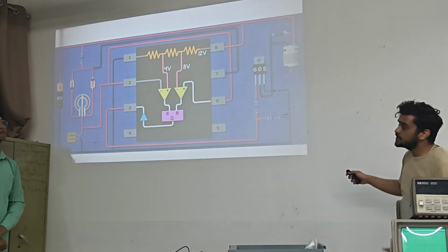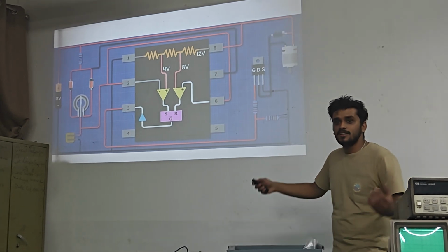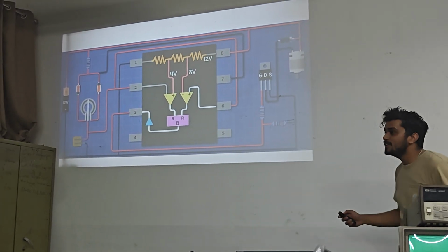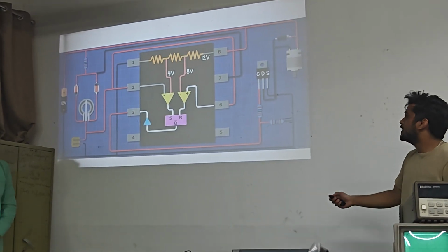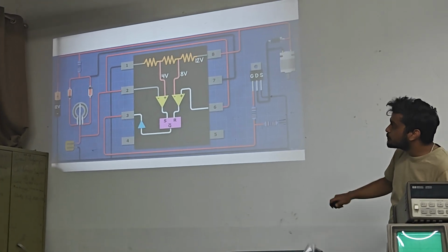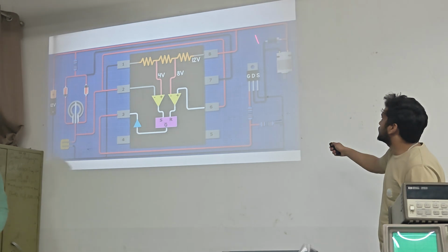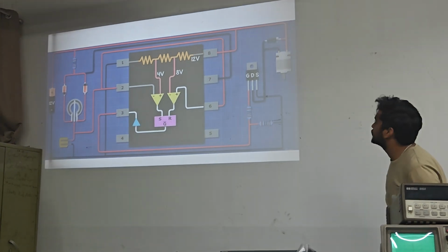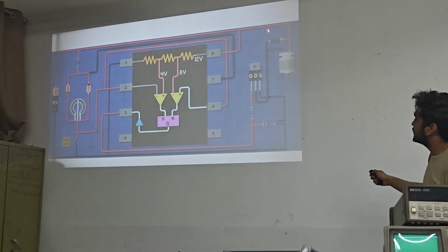But in this path, this motor will sometimes generate very high current, right? Basically, greater than 300 milliamperes can be generated over here. So this diode can only handle current up to 300 milliamperes, but this diode can handle current greater than that. So over here we have used this diode and this.